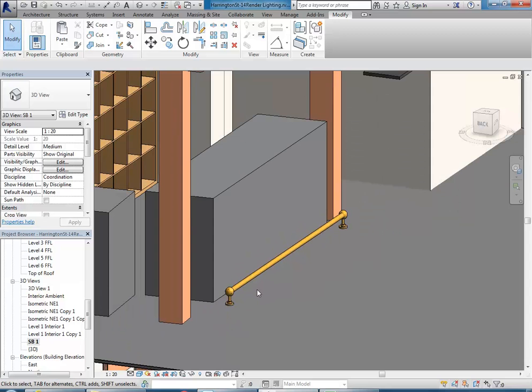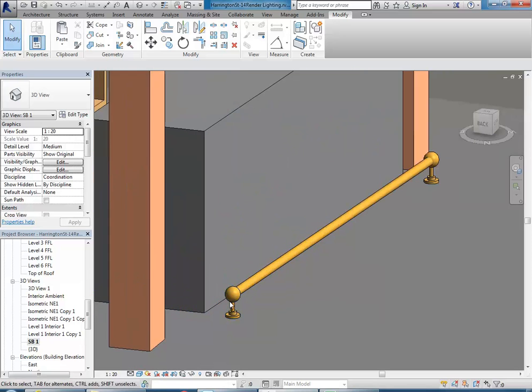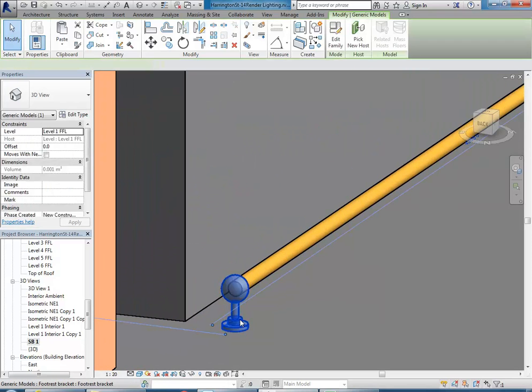So that's good. So we've looked at modelling extrusions using a plane that's not the ground plane. So it's really just using that set option, and sometimes you'll need to make a reference plane to choose, or you can choose a surface.